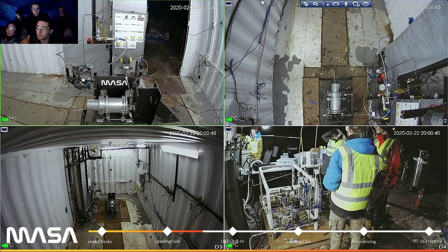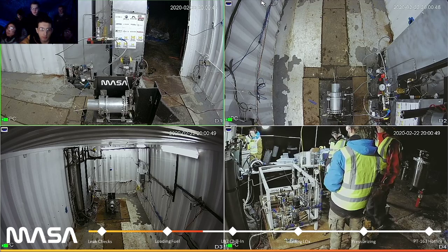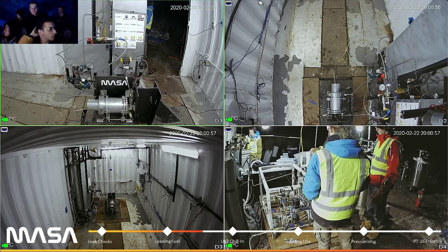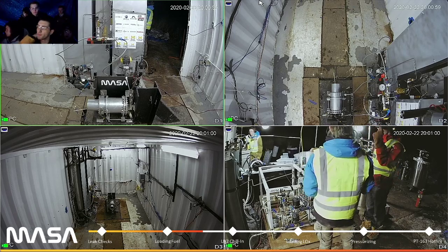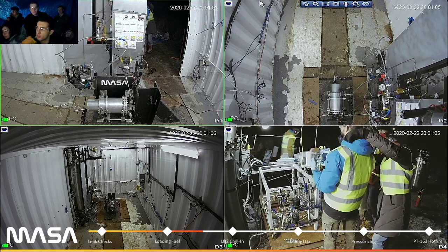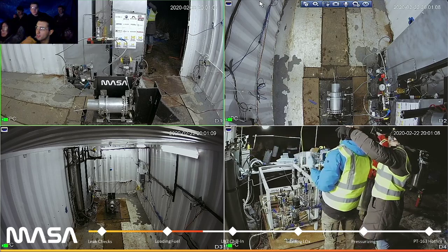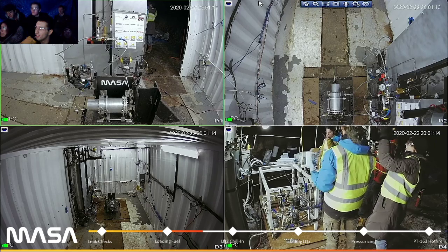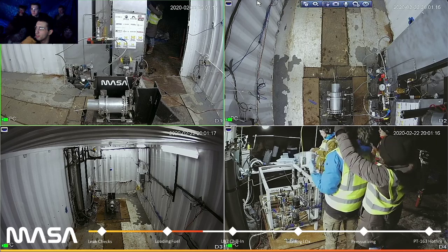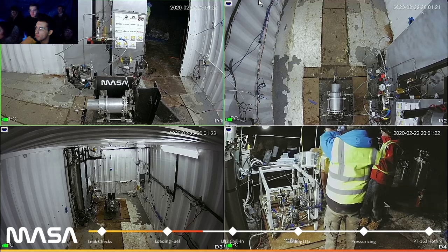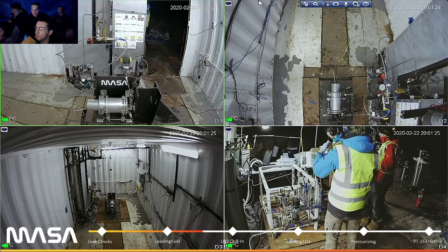But mostly, this is kind of a test of the propellant feed system and the valves. Since the engine has already been tested to 1 second duration, we're pretty darn sure it's going to be fine for 2 seconds. So it's mostly a test of the entire ground system, avionics, controls, auto sequences, valves, tanks, regulators, things like that. The engine will start showing some stress maybe at between 4 and 8 seconds. That's when it'll really start being challenged, and so we'll see how hard we can push the engine.